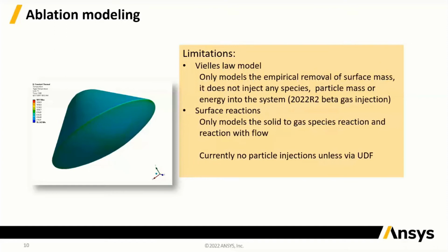We can also switch, depending on the Mach number, back to the pressure-based code, but we have some limitations in the number of species we can work with also. I think we're limited to 50 right now with the density-based code. We're unlimited with pressure-based.